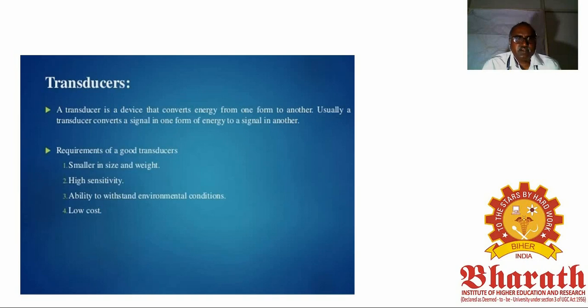The requirements of a good transducer are listed as follows. First, it should be smaller in size and also in weight, so that it can be fitted or manipulated very easily. Next, it should have very high sensitivity.